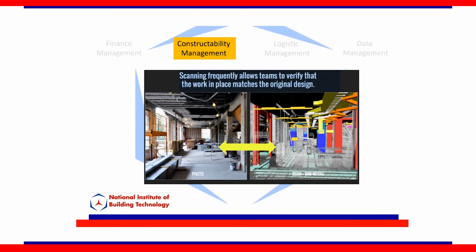Constructability and point cloud. The first one is we talked about as-built. This line really represents what the reality is. So if you're constructing it, right? There are products out there that are scanning every day. So you construct something, after it is built, you go and scan it, and then you come back and look at what has been done in conjunction to what it was supposed to be. So you have a model that was supposed to be built. But let's say the column moves by 2 inches, the bus duct moves, the duct moves, the pipe moves, whatever, anything moves, the scanning catches it.